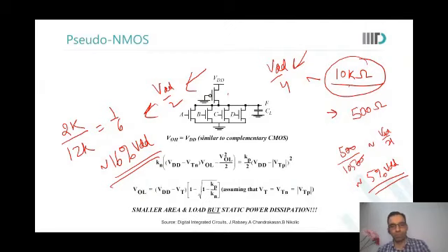At the VOL, at the output, I want the exact VDD pair. So this 16% and 5% I shouldn't get now; I should get the exact VDD. No, but VDD you will get. Yeah, but I'm getting this variation like 5% and 16%. Yeah, that is dependent on inputs. That is the challenge with ratioed logic. But even 16% of VDD will still be considered as 0, much lower than VDD by 2. The other case is where the problem is.